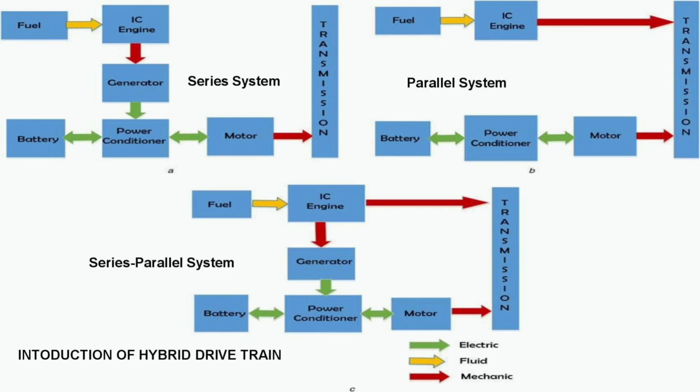However, a series hybrid drivetrain has the following disadvantages. First, the energy is converted twice and this reduces the overall efficiency. Next, two electric machines are needed and a big traction motor is required because it is the only torque source of the driven vehicle.